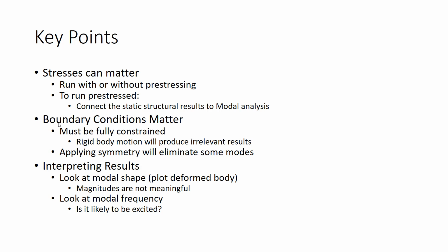The other thing to know is symmetry will eliminate some modal frequencies. If the mode shape is not symmetric with the geometry, then it will not be found by the solution if you just do a symmetric model.